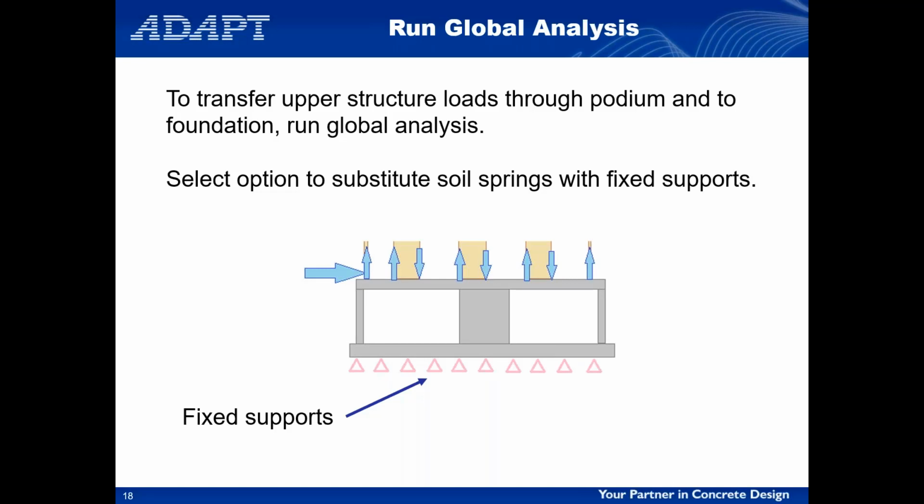And we want to make sure that when we run the global analysis, now remember, we had modeled the soil springs. So one thing that catches people by surprise sometimes is if you just go into that analysis, you get the full structure soil interaction, which is great, but you get a lot more flexibility and distribution of the loads based on the actual, full flexibility of the structure. Plus, it takes longer to analyze. In most cases, I've seen that our clients are satisfied with assuming that the loads are going to be transferred to the foundation based on the assumption of a fixed and rigid foundation to begin with.